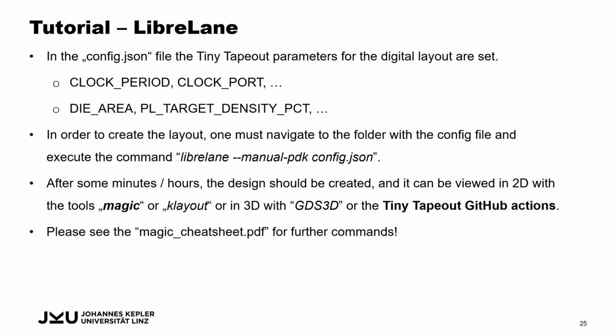And depending on your design, after minutes or hours, the design should be created, and it can be viewed in 2D with Magic or KLayout, or in 3D with GDS3D, or as I said before, with the Tiny Tapeout GitHub actions. And these GitHub actions work quite nicely. And if you use Magic as a layout viewer, then you can also check out the Magic cheat sheet for the commands and how to handle this tool.